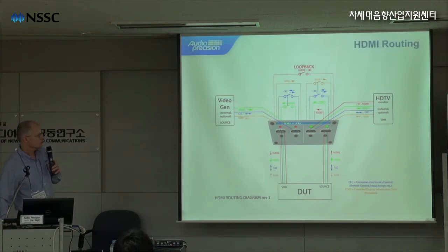Inside the instrument we have a loopback for audio, so we can generate a signal out of our source and analyze it on the sink. We also have the ability to send EDIDs and get them back, and we can also send and receive CEC commands.